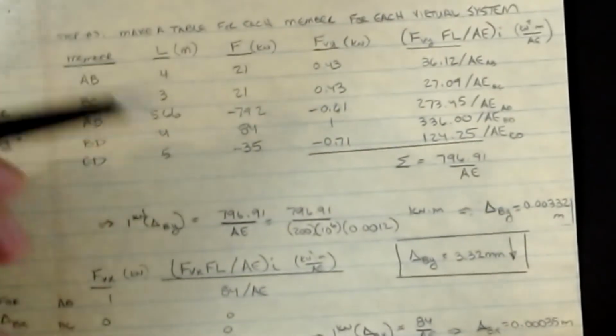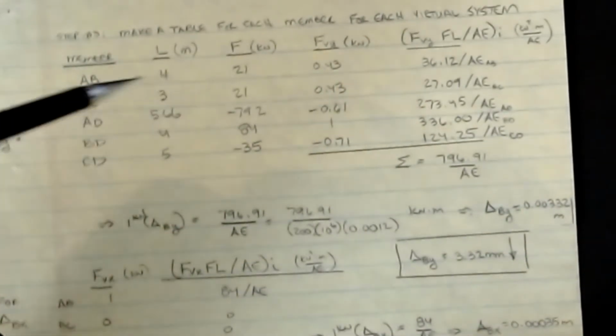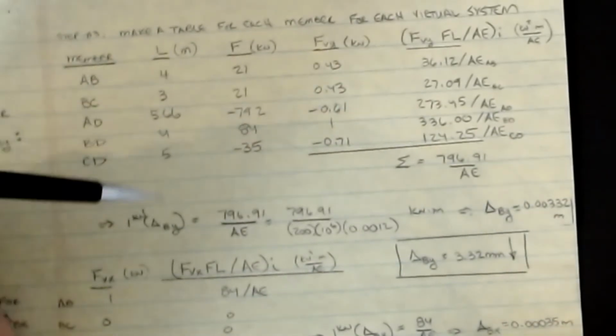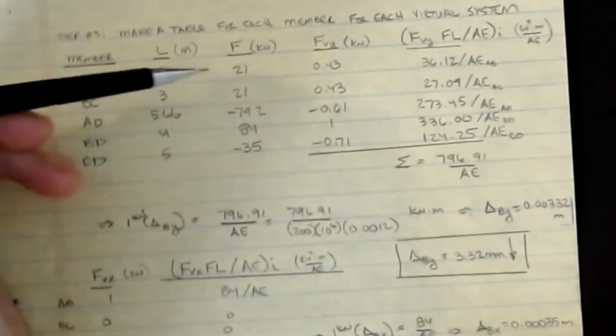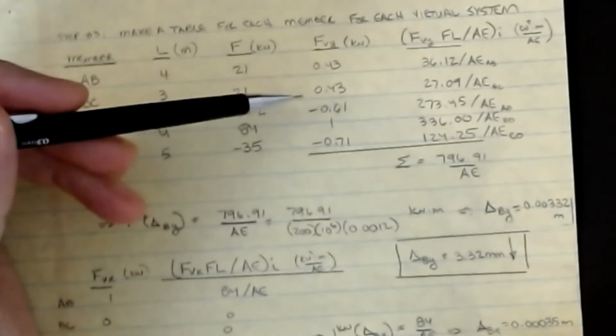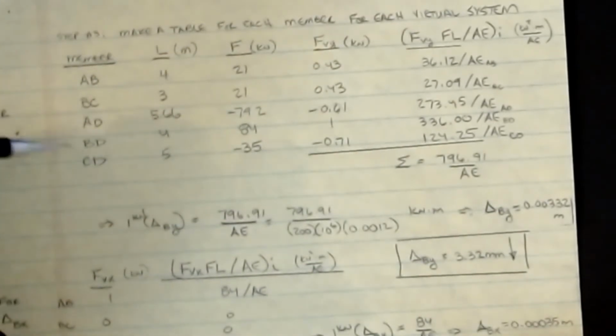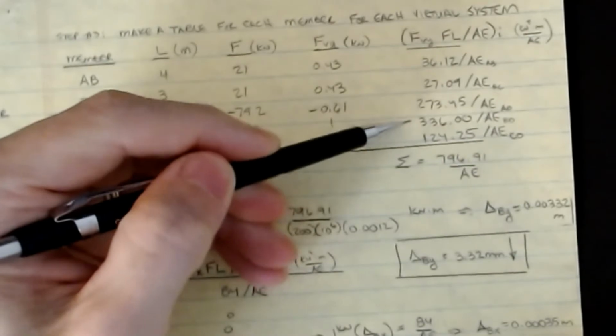So you can see it gets a little long, especially for big trusses. You have a lot of numbers happening, but they're all contributing. But something interesting shows up in here. You really quickly see which member is doing most of the work in the deflection. So for example, if you look at BD for the vertical direction, that vertical member is the one that's contributing the most to the work energy.